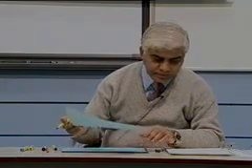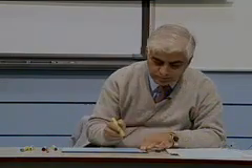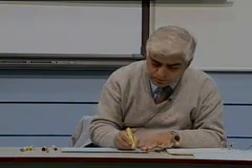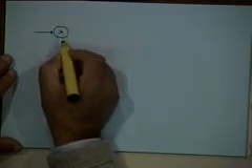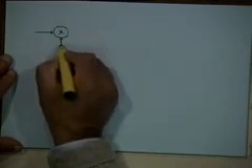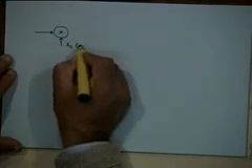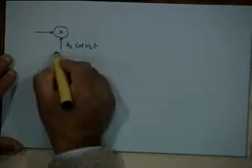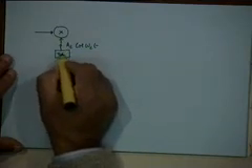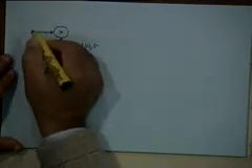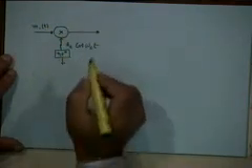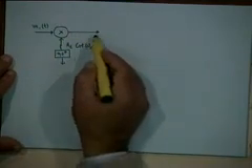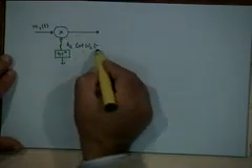Okay? To put it in the form of a figure, you have a multiplier for Ac cosine omega ct. Let's say you have a 90-degree phase shifter here. Your message signal m1(t) comes here, and this is your modulated signal m1(t) times Ac cosine omega ct.